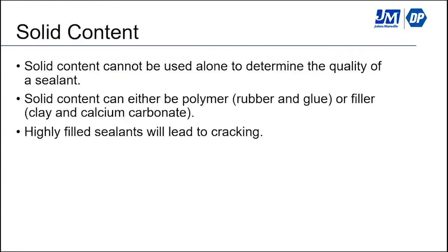Solid content. The reason I have this on here is kind of a warning, and it's one of the most common things I run across, both with contractors and with engineers. Solid content is not a determination of whether a sealant is a quality sealant or not.